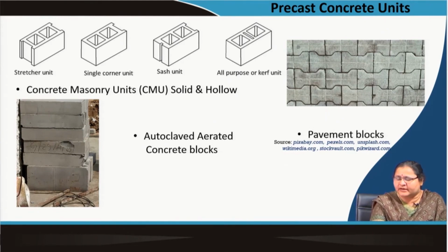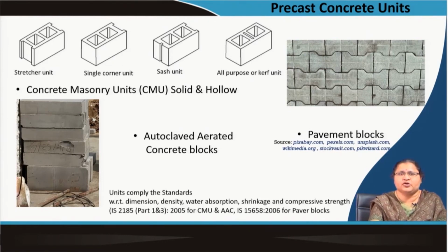You can see this is a plan view of the pavement block where these pavements are actually one set beside the other, and you can see it is locked. So, this is totally a dry way of doing it, and it is mostly done in parking areas, on footpaths, etc. So, all these are maintaining or complying with the standards with respect to dimension, density, water absorption, shrinkage and